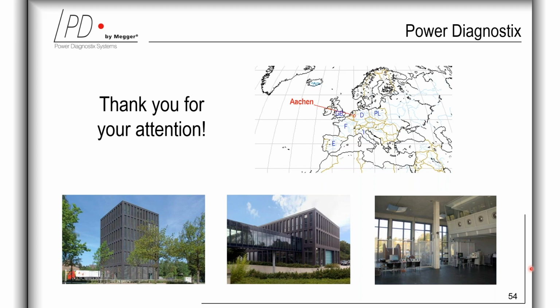As Sebastian mentioned, which equipment is mainly affected by partial discharge? Not easy to answer, but all kinds of electrical equipment where you have high electrical fields can show partial discharge and internal defects in insulation material. And it's not a question of the voltage level of the asset, it's a question of the internal electrical field strength, which is then causing partial discharge.